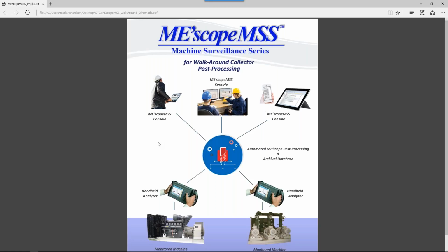Now the difference between SDI and MAC is that SDI actually takes the difference between the two shape vectors, and so it's computing a difference, whereas MAC is simply telling us whether the two shapes are lying on the same line or collinear with one another.